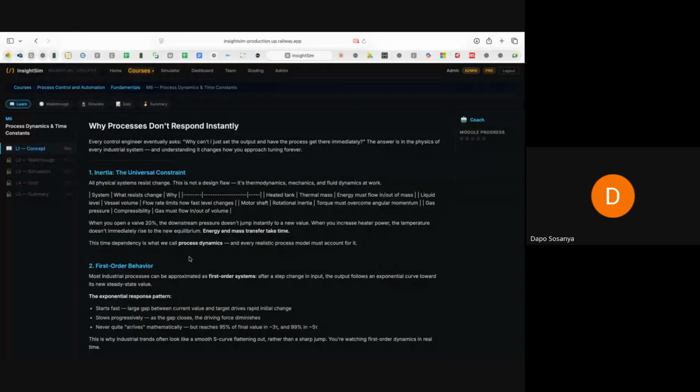An experienced programmer, if he sees that the process lag or the PLC scan time is too much, will read that sensor maybe 2 or 3 times within the scan time. It will dedicate other rungs or add conditions to check the state of that transmitter a few times during the scan time, so that the process will not be exposed to dangerous conditions while the PLC is running its scan. I hope this makes sense to you.